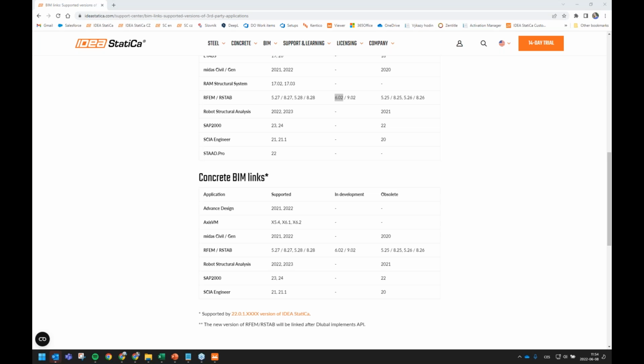You will see that the model would not even start to calculate, or after you calculate it and display the deformations and stress and strain, you would see that it totally broke. So you have to use it every time it's, let's say, a pure hinge.